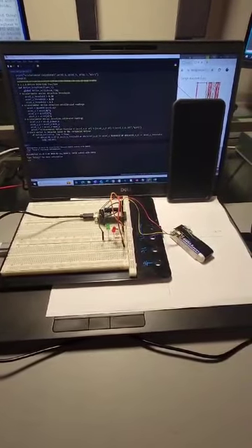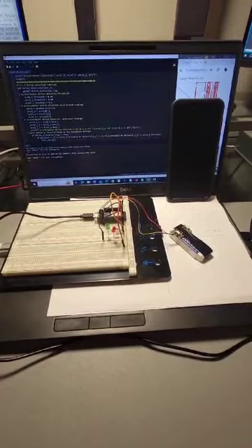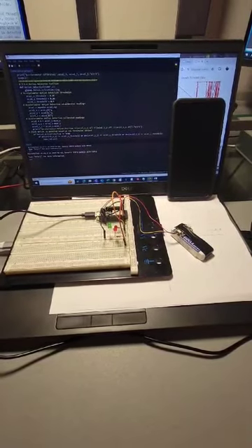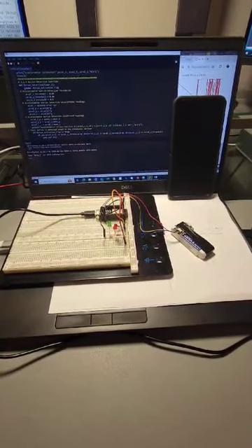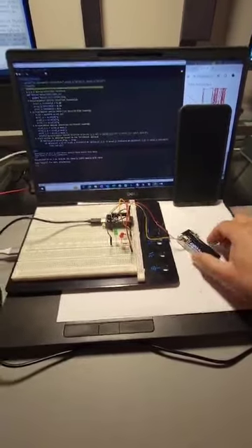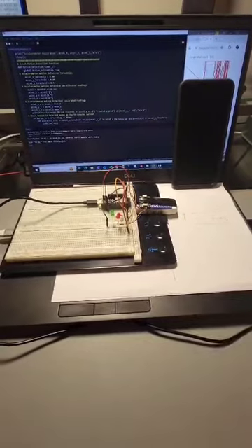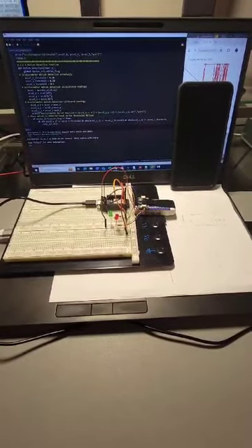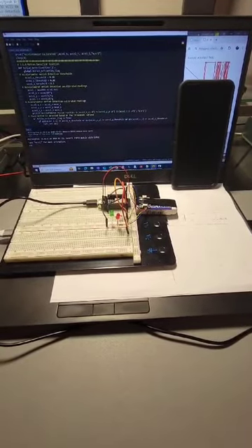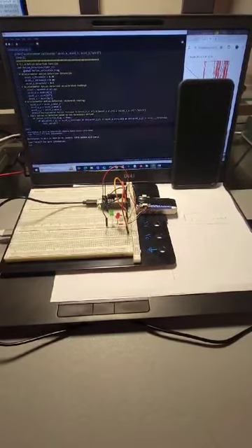The first step of the project is I had to connect the ESP32 board to my phone Wi-Fi hotspot internet. Then I needed to initialize the MPU-6050 using the I2C serial communication protocol, using the device address of the I2C bus from the datasheet.